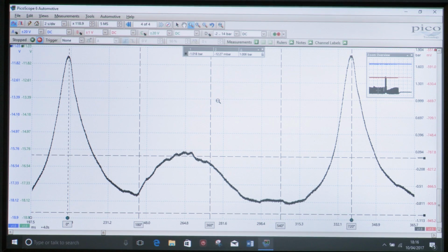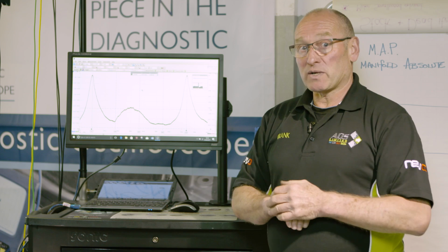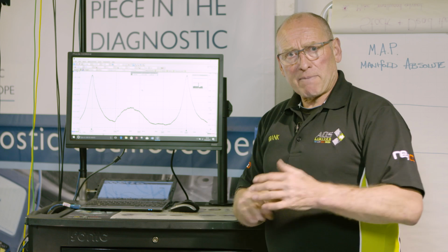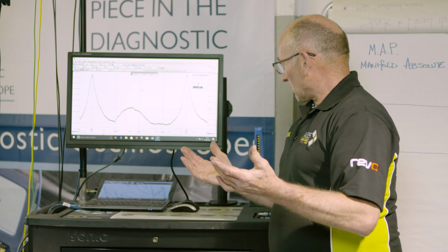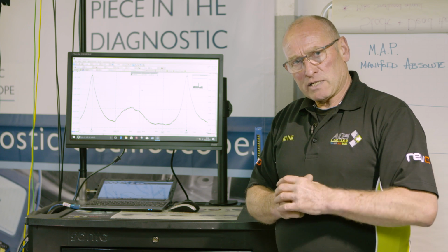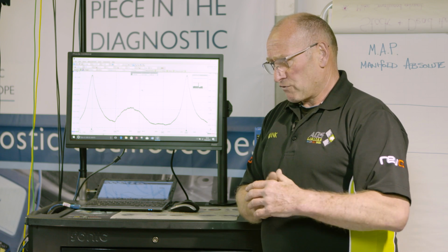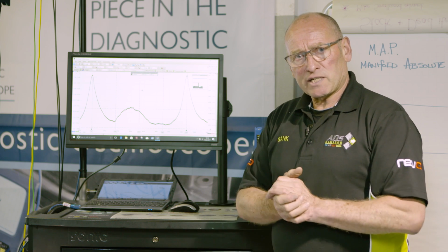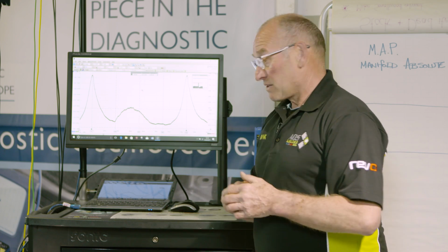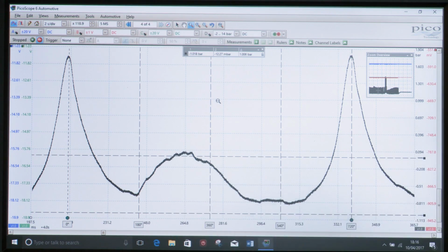Had the exhaust been blocked, or let's say the exhaust valve didn't open for whatever reason, then that pressure, of course, would increase dramatically, depending on how bad the blockage was. So, in effect, I can think back in years gone by when I've suspected a blocked exhaust, and I've dropped the exhaust pipe to run the engine to see if it's fixed the problem. Well, there's no need. There's your evidence. This exhaust is not blocked. Had it been blocked, that would have increased dramatically.